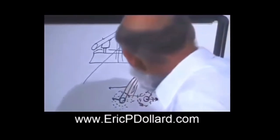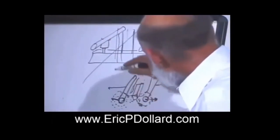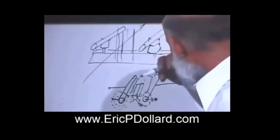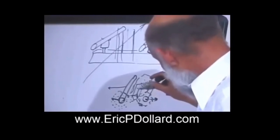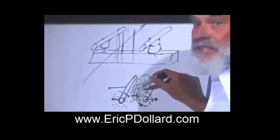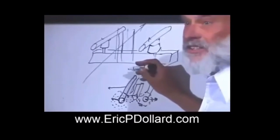Now if I put a chunk of iron or some kind of magnetic material in between those wires, okay, that magnetic material is going to suck in the magnetism, and again there will be more magnetic storage capability inside this electromagnetic structure. But with the iron, if I keep increasing the current situation of the magnetism so that the iron can't hold any more, the iron goes into what's called saturation, and it will no longer hold any more magnetism, and all the rest of the magnetism that's produced by the generating station will have to continue to exist outside the iron. It's what's called a saturation condition.